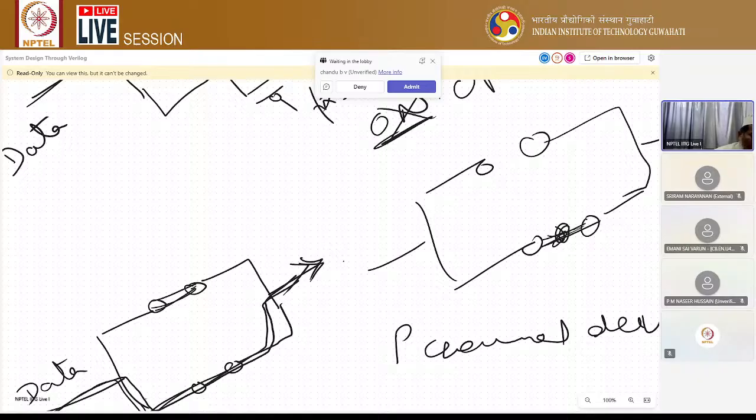Both can be on, connecting input to output, so there is a short circuit path between input and output, but also a parallel path. In the other case, one is off and another is on, and through this path the input will transfer to the output. Only the case where both are off, open circuited, has no path from input to output. So for all the combinations we get the outputs accordingly.